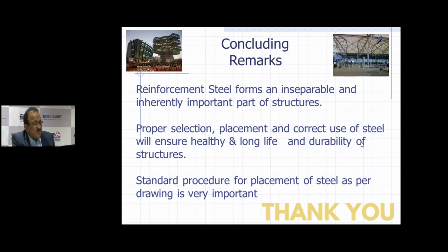How can you avoid corrosion of reinforcement if the procurement is done earlier at the construction site? This is Vadiraj Rao and NR Rao asking this question. We have to protect the steel from corrosion, as I mentioned in how to store. Number one, cover it with plastic sheets so that the moisture and atmospheric humidity do not cause corrosion.